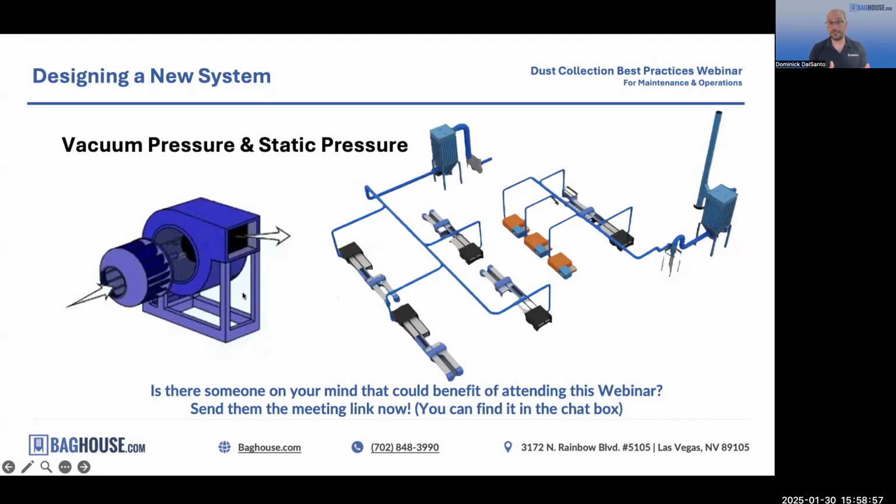And as Matt explained, what does that mean? It means that when there is 10 inches of static pressure in front of the fan, so all the ductwork and the baghouse together make 10 inches, this fan will create 10,000 CFM of airflow through it, right? That's a simplification of how fans work, but that's the basic idea we want. This is important when you're procuring a system because when you write your spec for what kind of fan you want or how much airflow you need, you have to tell the fan supplier whether you need this much static pressure or a lot of static pressure.